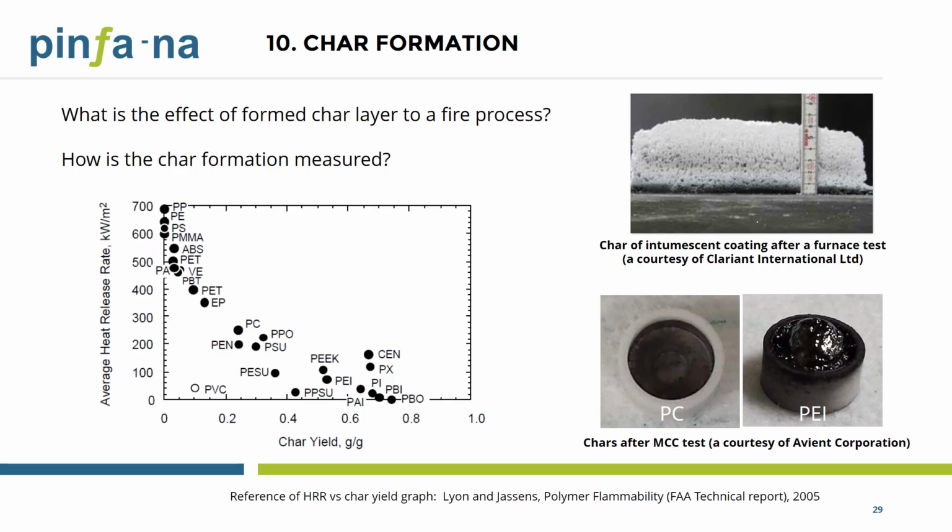An intumescent material, when exposed to a fire, forms a char layer that isolates the heat of the flame and gas phase from the underneath material. Meanwhile, the char may reduce the smoke release due to its barrier effect to the pyrolysis zone. So a good char layer formed in the burning process protects the unburned material underneath the char.